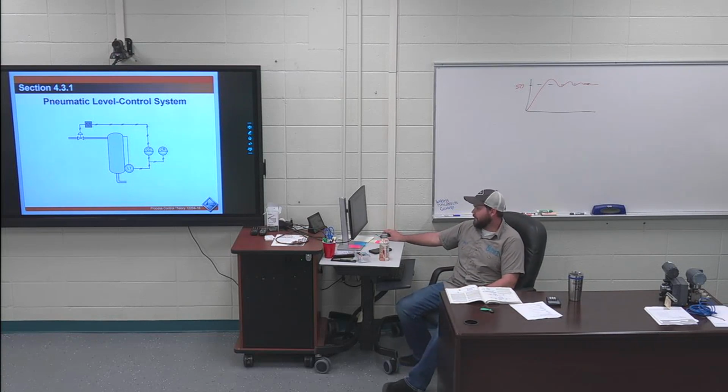So right here is my differential pressure transmitter, right? Where is it getting the two pressures from? What's the question? So this is my level transmitter right here. It's a differential pressure transmitter, for level on a tank. Where is it measuring the two levels from on this tank? What part of the tank is it measuring from? Top and bottom. Because the bottom is going to be its most head pressure, and the top is going to be its zero. And sometimes this is called a leg or the high leg.